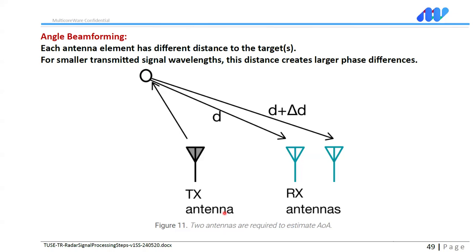So at ADC, you would have very, very low SNR signal. And at each step, your processing gain goes up. And in the first 2 steps, range and Doppler, usually it's sufficient depending on the application. Then you select your target, you select the data, you sparse it, you throw away most of it, you keep probably 10%, maybe less.